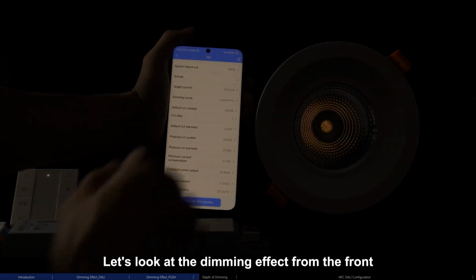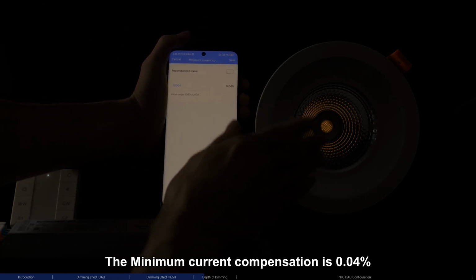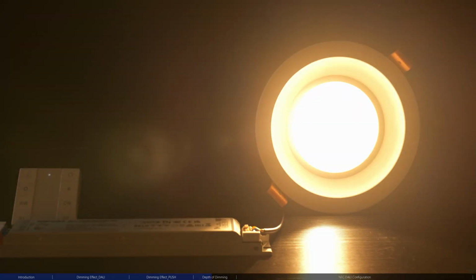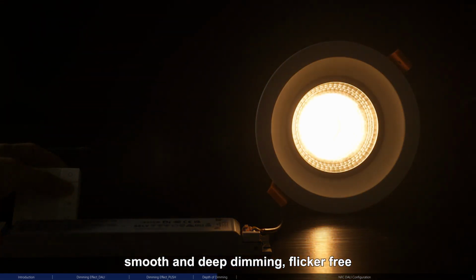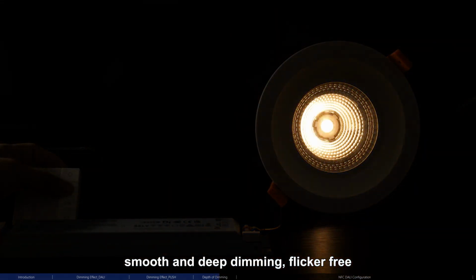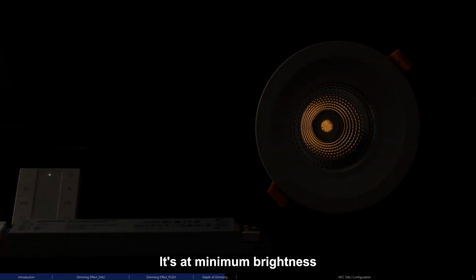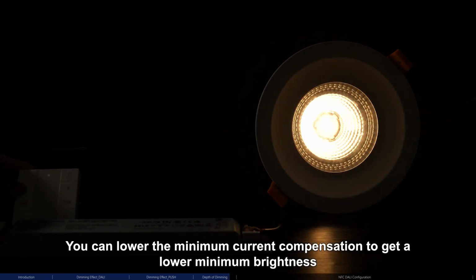Let's look at the dimming effect from the front. The minimum current compensation is 0.04%. You can set it lower to get a lower minimum brightness. On. Long press to reduce brightness. Smooth and deep dimming, flicker free. It's at minimum brightness. You can lower the minimum current compensation to get a lower minimum brightness.